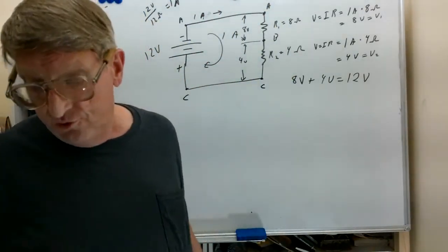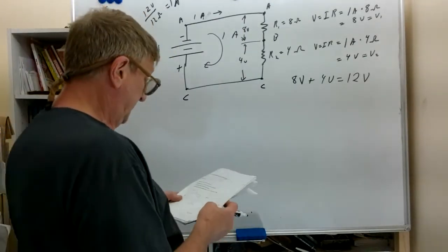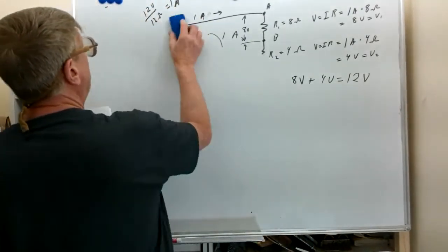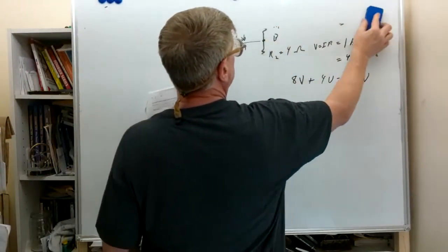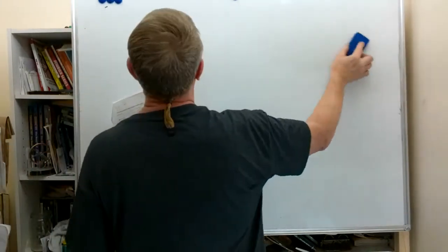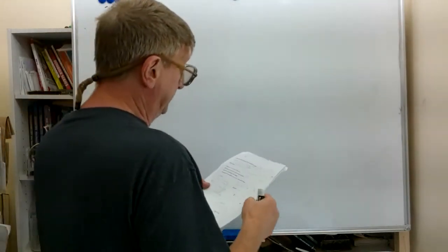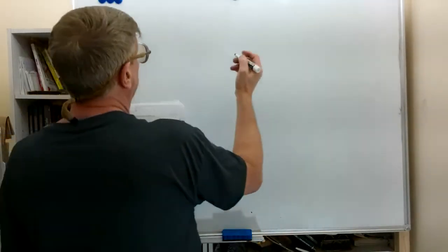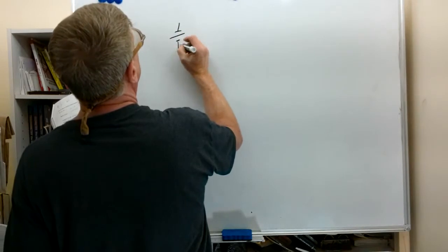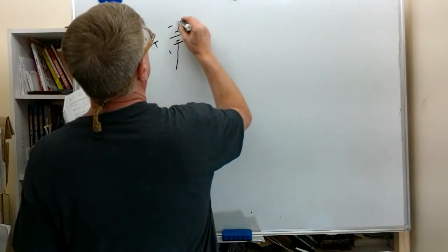And we'll do a few more examples on that. We can use that knowledge that the voltage drops across resistors, loads, whatever you want to call them, add up to the same voltage as the supply to determine a few things. And I'm going to give you, we'll call this VT. I'm going to put polarity on it, but it's not really necessary.